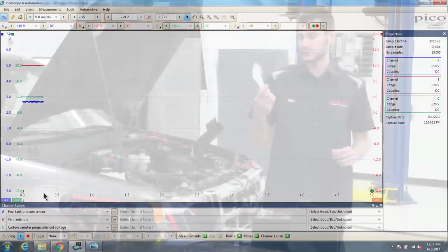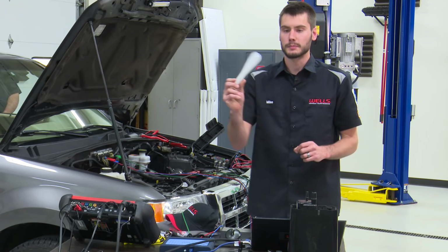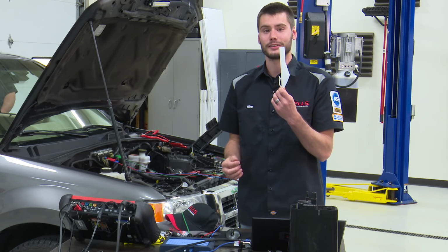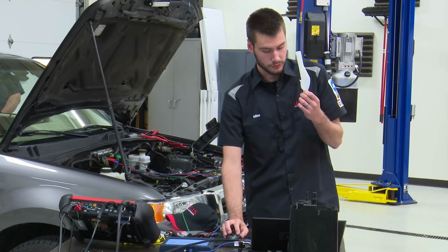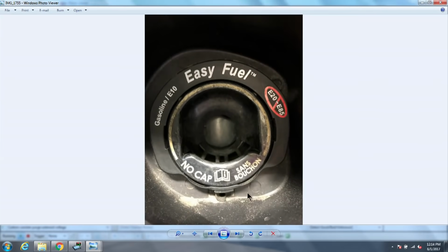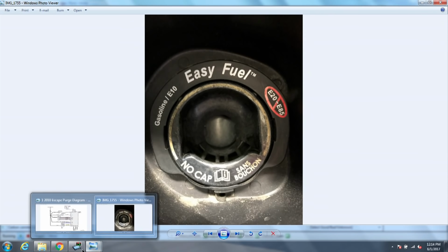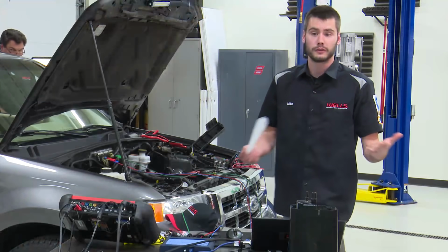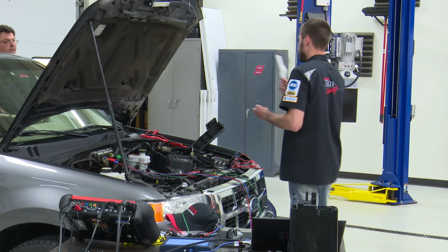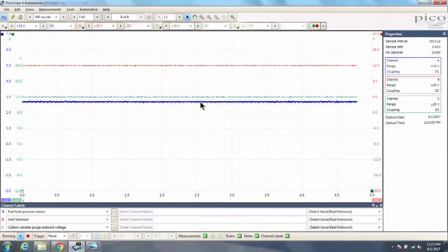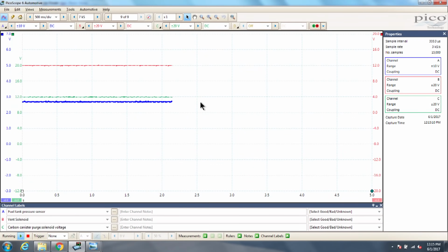I'm going to take this super special cool tool that's usually mounted right next to that locking lug nut tool that you can never find. It should be somewhere in the vehicle on a Ford. This tool is to open the fuel filler cap, essentially. This tool fits right in here. And what I'm going to do is open the system, just like on the other system where I took the cap off. I'm going to have Fritz open that. We're going to watch our fuel tank pressure to see if we generated any pressure or vacuum inside of the tank. So Fritz, you want to shove that in there and see if we did anything as this thing was sitting? Yeah, go ahead. We'll see if we get any change.